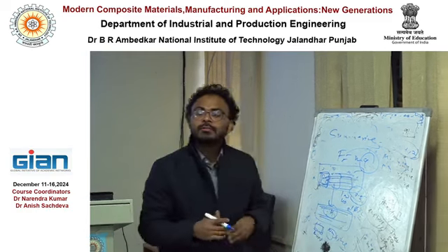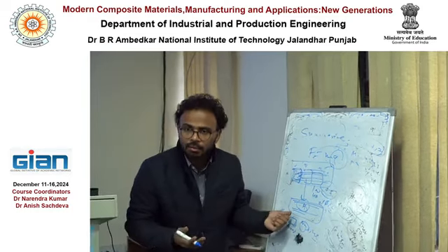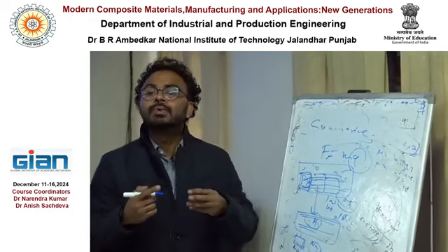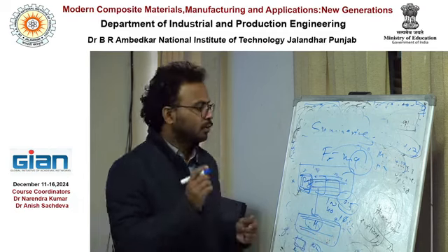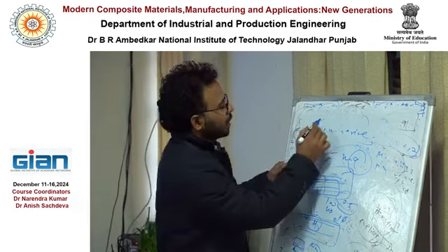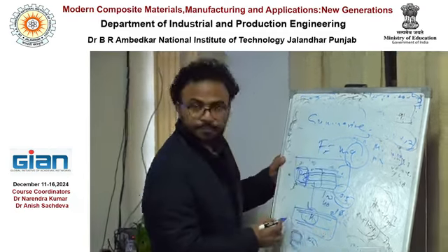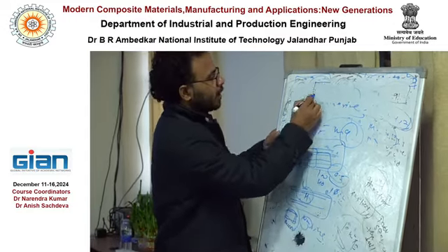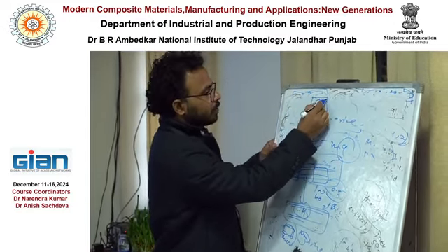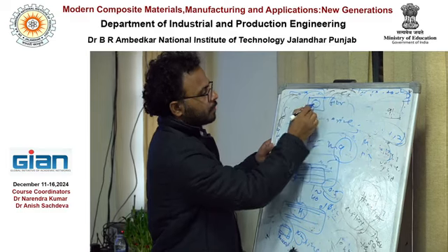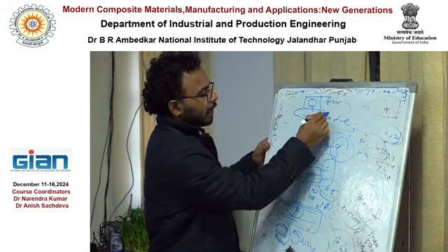And what do you want to calculate? The mechanical properties of this? You want the E1, E2 because you don't know them. Then what can you do? I will suggest: first create this one, a small part like this. So this is your fiber, this is your fiber, and this is the matrix.